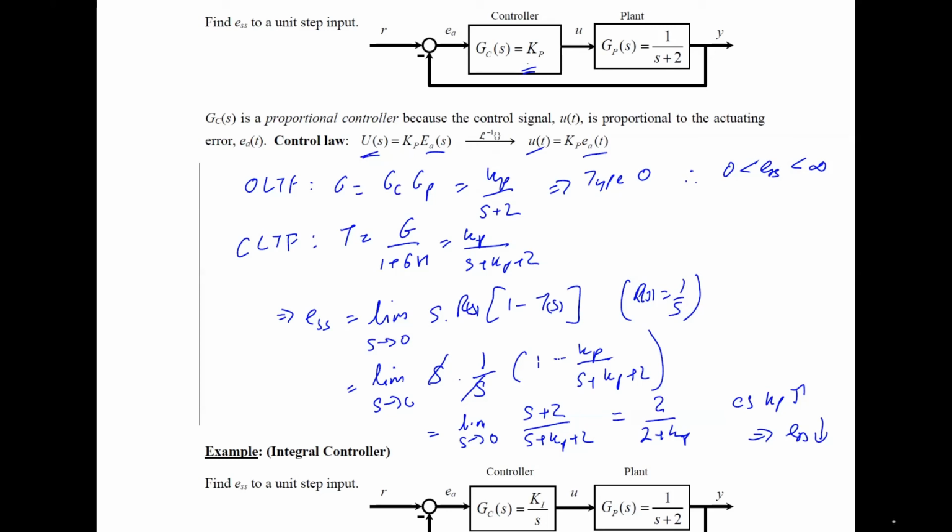let's say for some system we were trying to do position control, we see an error of 1. We increase the proportional gain, and from 1 meter, let's say the position error decreased down to 1 centimeter. If we are happy with 1 centimeter of position error, then fine, we don't have to do anything else. So we have selected our proportional gain. In this kind of a system, we can increase the proportional gain and decrease the steady state error, but we can never completely eliminate it.